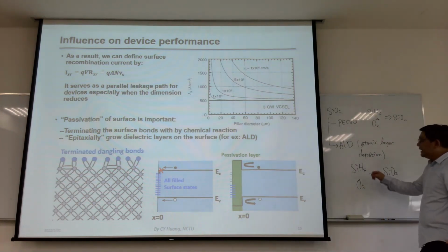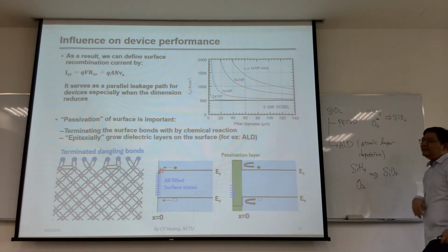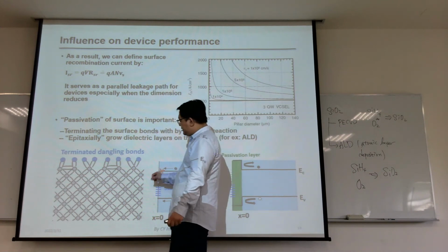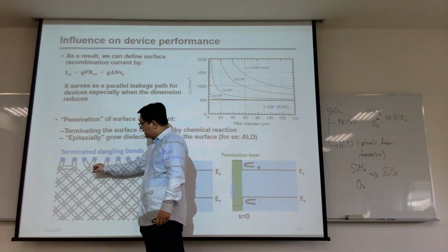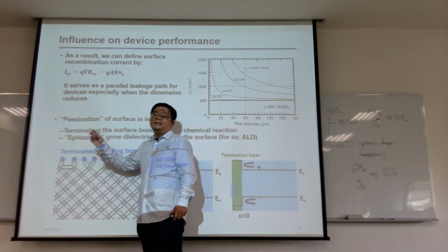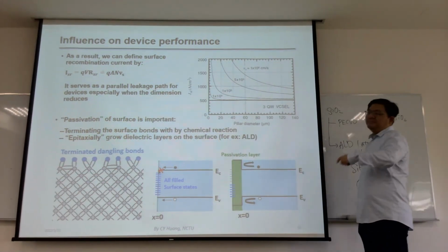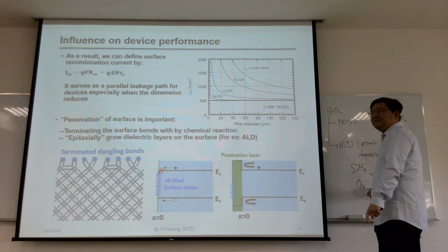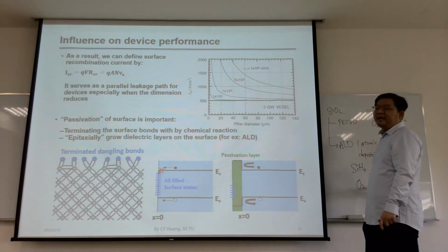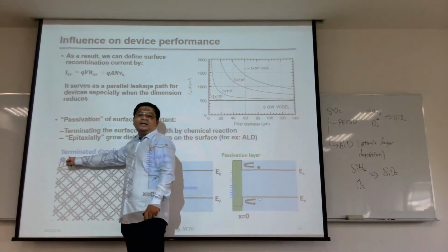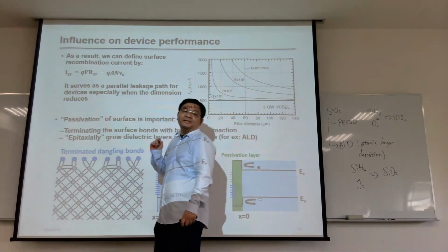We flow the silane first and take a long time to assure each atom is covered by silicon. Then purge the sample, and flow oxygen in to oxidize every silicon atom upon the surface.